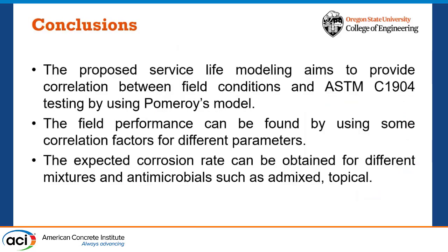So as a conclusion, the proposed service life modeling aims to provide correlation between the ASTM testing and field data by using the Pomeroy model. And we can provide this by using some correlation factors for different parameters. And the expected corrosion rate in the field can be computed for different mixtures or antimicrobials or admixtures.